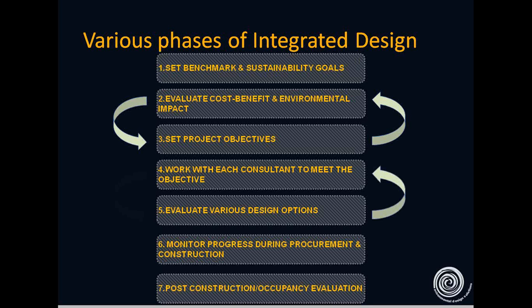Some examples of building simulation applications. First, let's start step by step, and these also form the steps for the integrated design approach. The first and foremost task is to do the microclimatic analysis, because that will form the basis for each consultant, whether it's the HVAC, the lighting, the architect, or the structure. These form the guideline for doing the analysis. So there is microclimatic analysis, solar analysis, wind analysis, and weather data analysis.